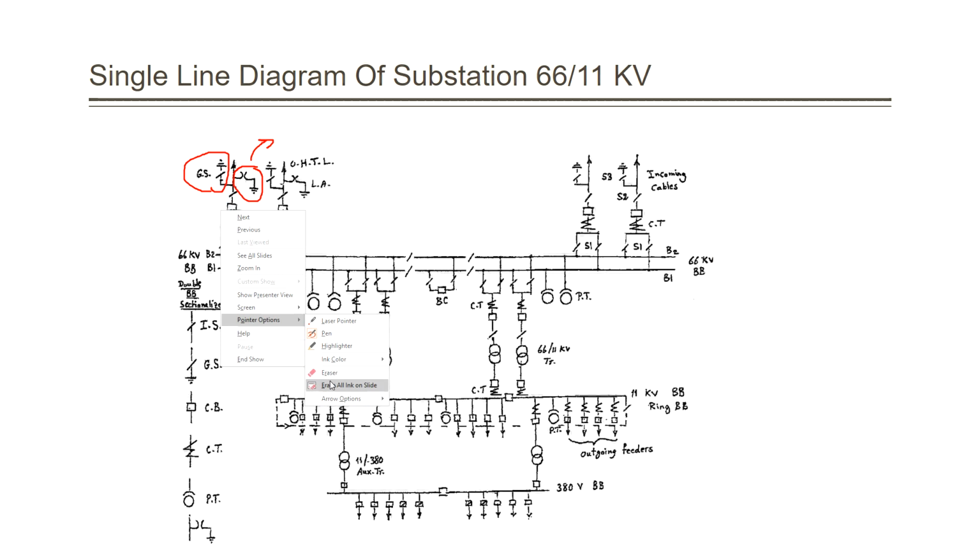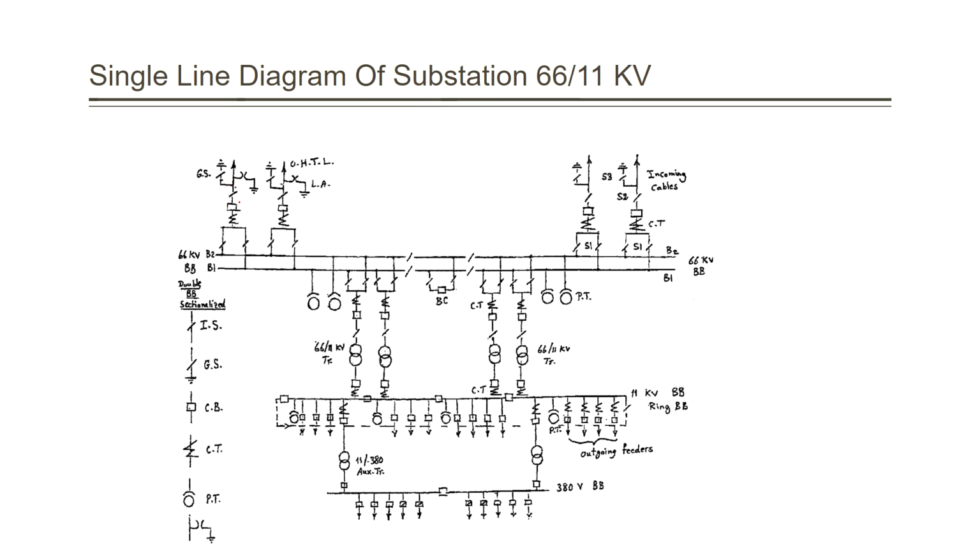There is also the isolating switch. This isolating switch is used for switching on and off, and of course it switches on and off at no load. Then we have this part, which is the circuit breaker. The circuit breaker is used for protection against short circuit.